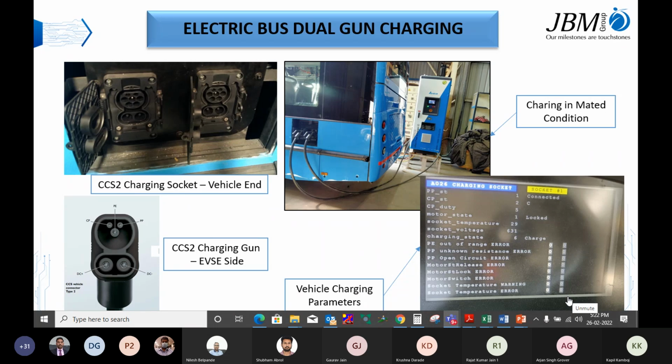Just want to know whether approximately we can go up to 1.5 minute, because as per DIN standards every time is decided that pre-charge time is limited to this time, the cable check time is limited to this time, like pre-charge 7 seconds, cable check is 30 seconds. So based on the operations the time is limited to 1 to 1.5 minutes. That is maximum time. Okay, it is a part of charging, including charging time, right? Yes.